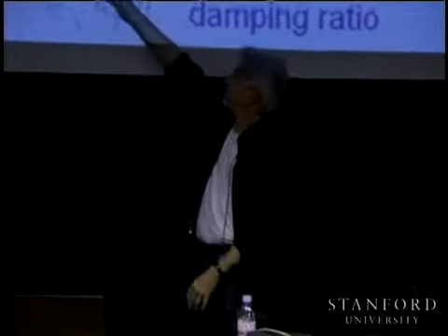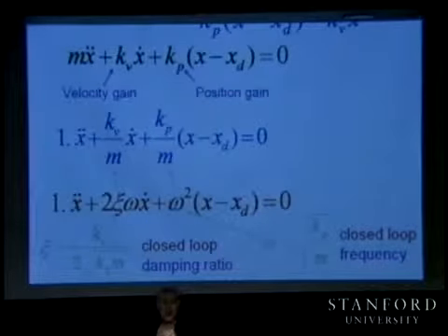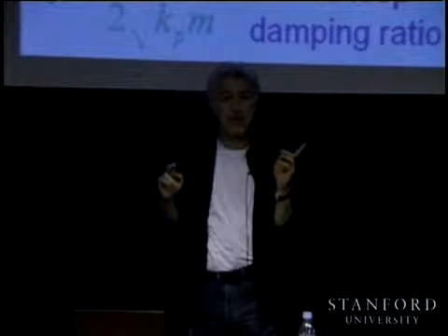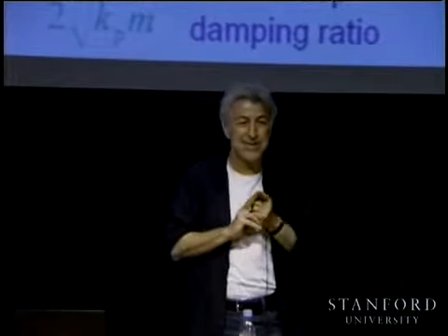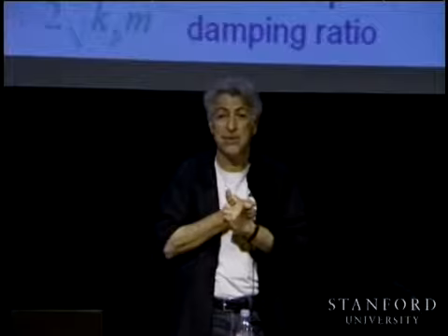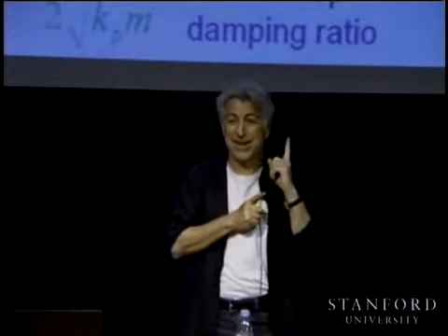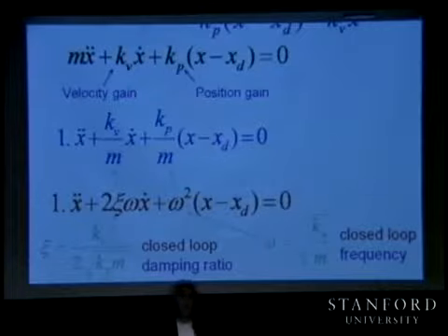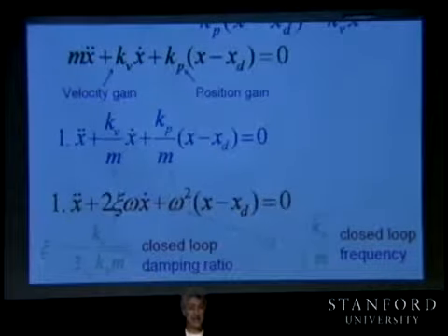Yes? High frequency and critical damping. So we want to have a critically damped system most of the time, so we will reach those goal positions as quickly as possible without oscillation. So Kv would be selected to achieve that value. And for that critically damped system, what is the value of zeta? Anyone remembers? It was only 2 days ago. For a critically damped system, zeta is equal to unity, 1. When zeta is equal to 1, that is when Kv is equal to 2 square root of Kp m, you have a critically damped system.